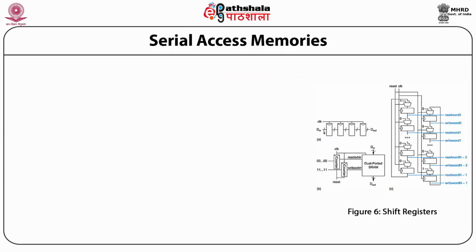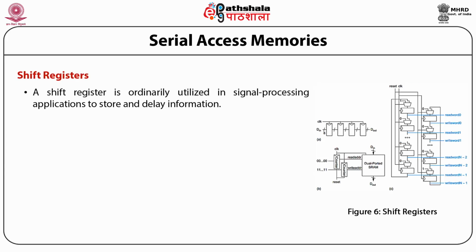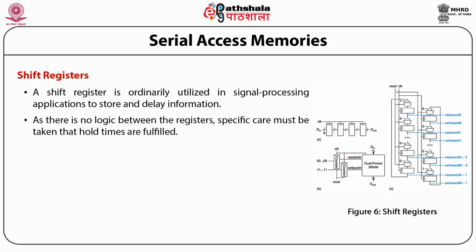Now let us discuss the shift registers. A shift register is ordinarily utilized in signal processing applications to store and delay information. This figure A demonstrates a basic 4-stage 8-bit shift register constructed from 32 flip-flops. As there is no logic between the registers, specific care must be taken that hold times are fulfilled.